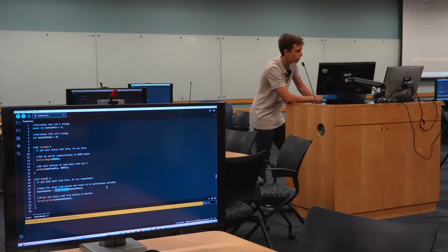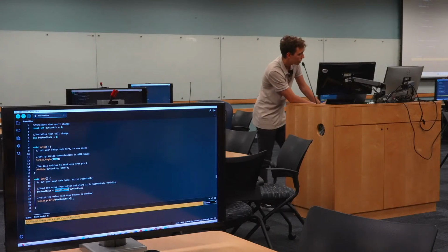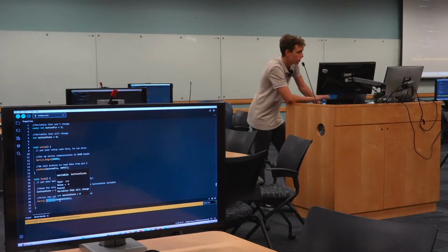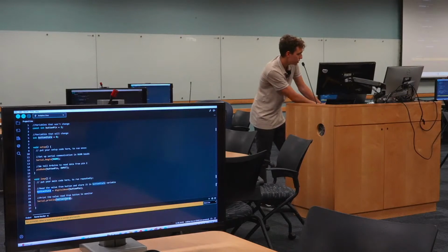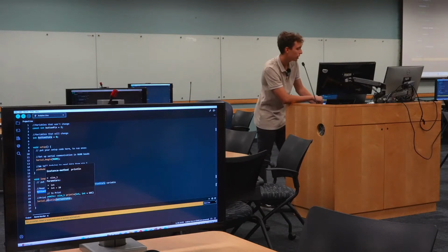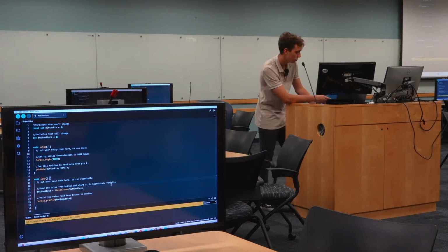If it's pressed, with a pull-down resistor, it's going to be 1 because the gate is closed, the energy flows. And if it's a pull-up resistor, it's going to be literally the opposite. And here, what you're saying is, use the Serial. Again, this is our main class that we are using from Arduino. And we are calling the method println, which is basically similar to the System.out.println from Java or the print from Python. And you're printing to the monitor the value of the button. And that's a way of debugging the application in general, and now we see it with this particular project.